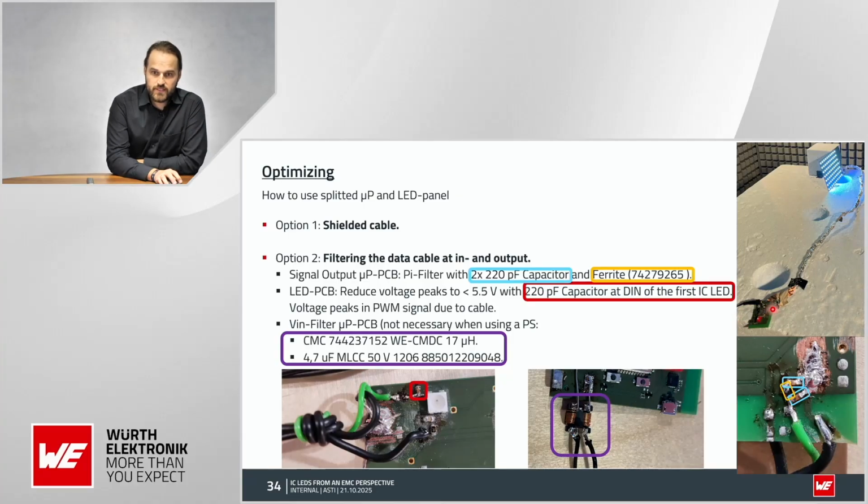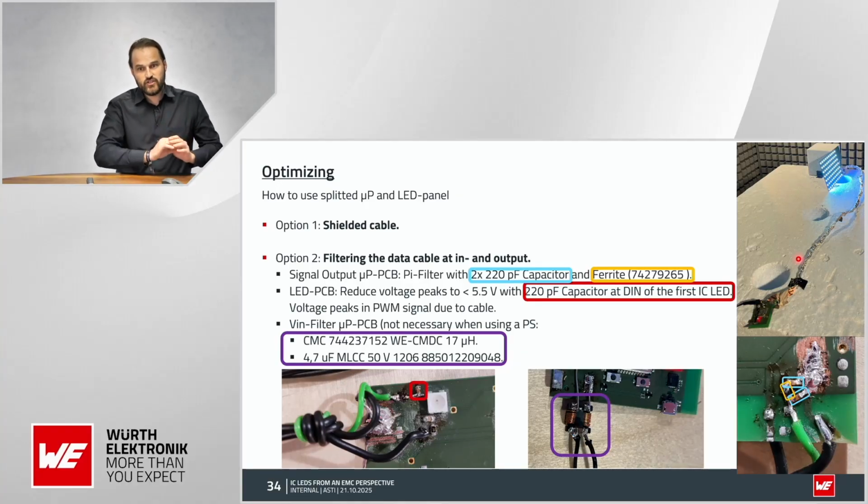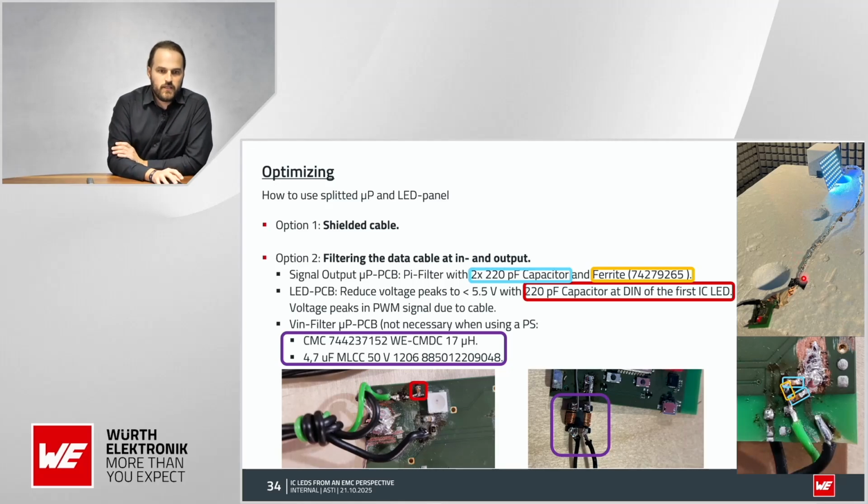What I'm doing is I'm connecting still VCC and the data string between both, and then I'm using both ground planes from the MCU and from the LED side, connecting this to copper tape and then the copper tape to aluminum foil. So we use the shielded cable to extend our ground plane. In the end, more or less, we are simulating a complete ground plane between both boards.